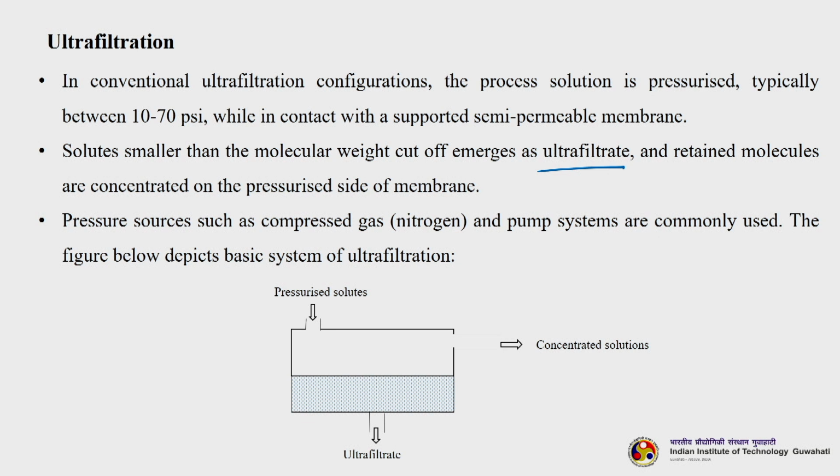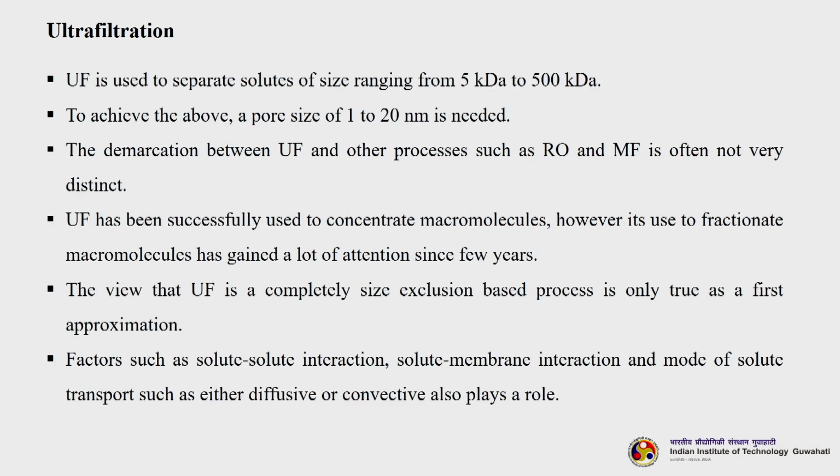So, your feed is coming here, entering, and then you get your concentrated solution, the retentate, and in the permeate you are getting the ultrafiltrate. So, ultrafiltration is used to separate solutes ranging from 5 kilodalton to 500 kilodalton. This is the solute size that can be separated, or you can say rejected, using ultrafiltration membranes.